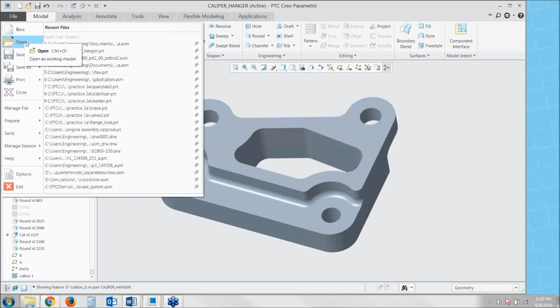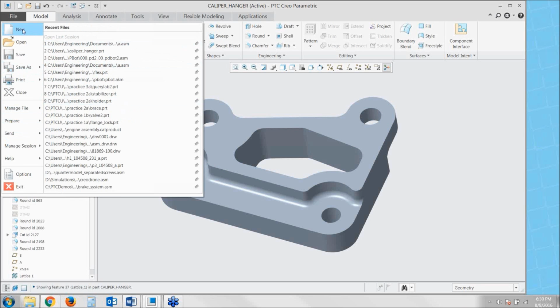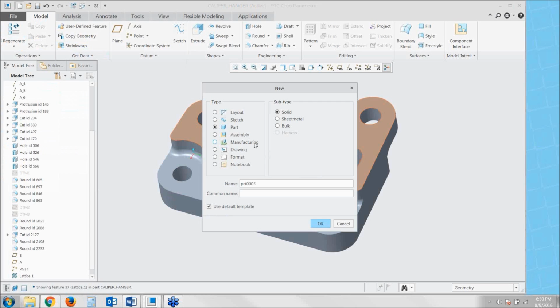Now, in order to also facilitate 3D printing, currently the way it's done, many CAD packages, whenever you have a design to go to a 3D printer, really most CAD packages will stop where they finish creating the 3D model, and then you would have to create a step file and do a lot of setup work on the printer end, setting up the part on the tray, checking for printability, and all these different other things. All of that you can now do from the interface of the additive manufacturing subtype of a manufacturing file.